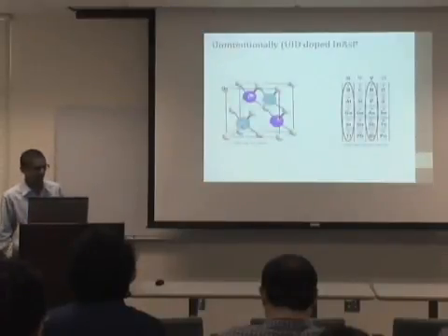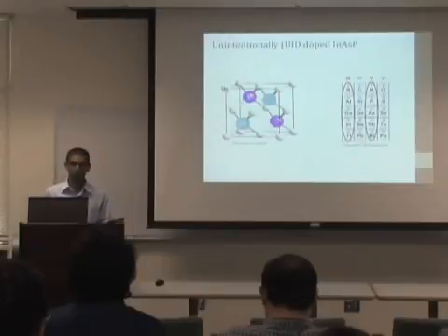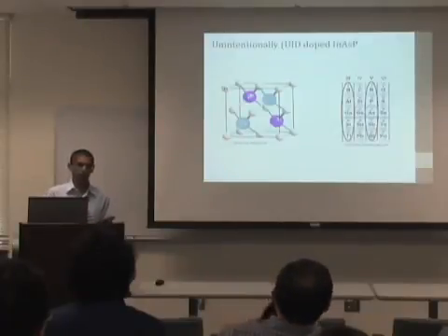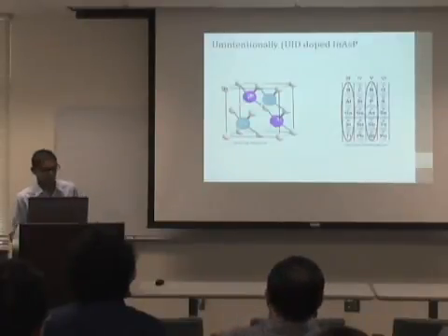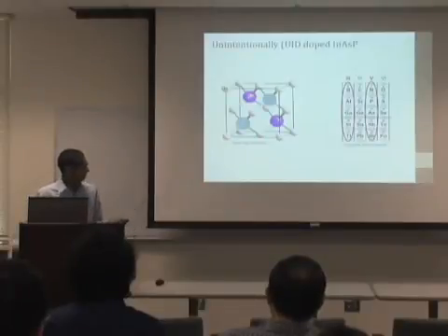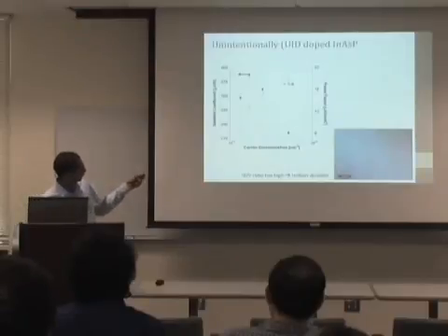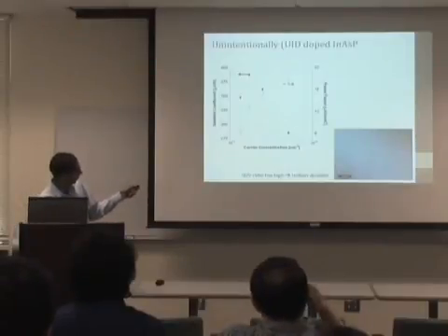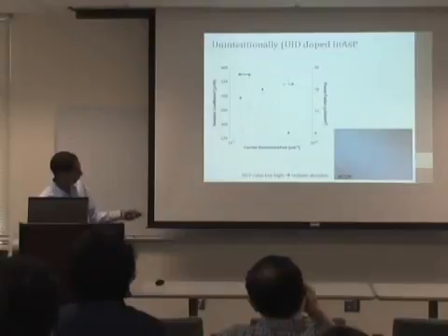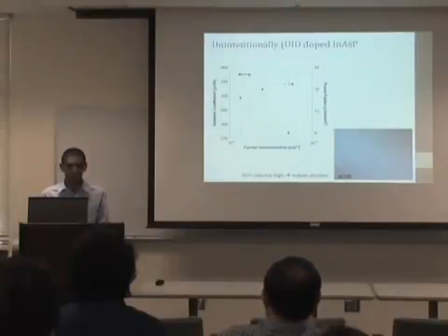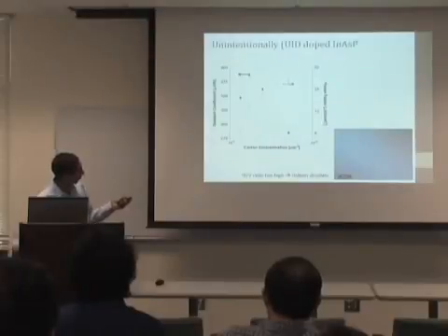And then we studied unintentionally doped, which we call UID, and that's without any dopant. It's just things inside our growth chamber may have incorporated into the material and donated charge carriers. And this was an indium arsenide phosphide lattice, and we noticed that the Seebeck coefficient does follow that trend, save for that anomalous point there, and we think that might be because we got these weird indium droplets on our surface. And then we see that our power factor is rising, but we still haven't quite reached that peak yet.